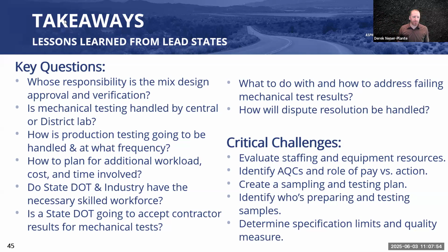Create a sampling and testing plan for your different types of projects, given your equipment, resources, turnaround, etc. That obviously is trying to balance risk, to sample enough, because we know our materials are variable. We know that testing it today versus testing it 3 hours from now, it's going to be different. We do not have a tightly controlled production process down to the millimeter. That's just the materials that we work with. So create that plan and adjust it as you have needs and challenges.